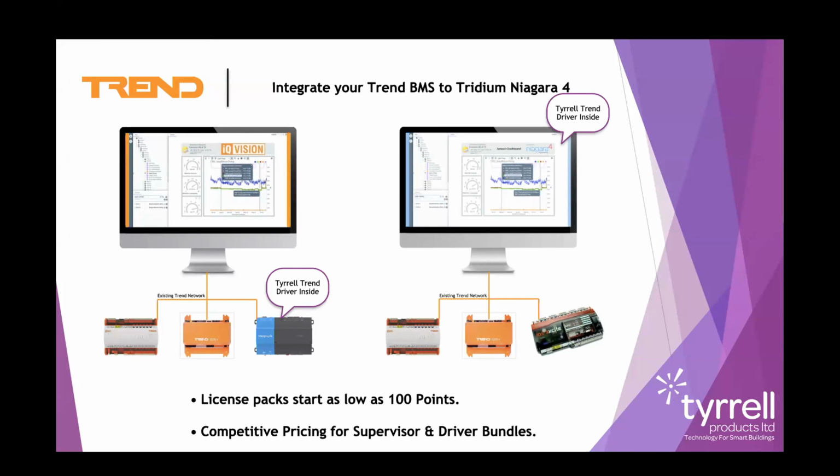In reverse of that, if you are upgrading, say, 963, which will not be supported from, I believe, January, you can install a native Niagara supervisor front end. You are not restricted to sticking with a trend flavor. You can install native Niagara, running the trend driver inside, and it will talk down to, as I said, legacy trend controllers and function as normal. Very minimal downtime due to the auto discovery and the discovery of points, knobs, switches, etc.